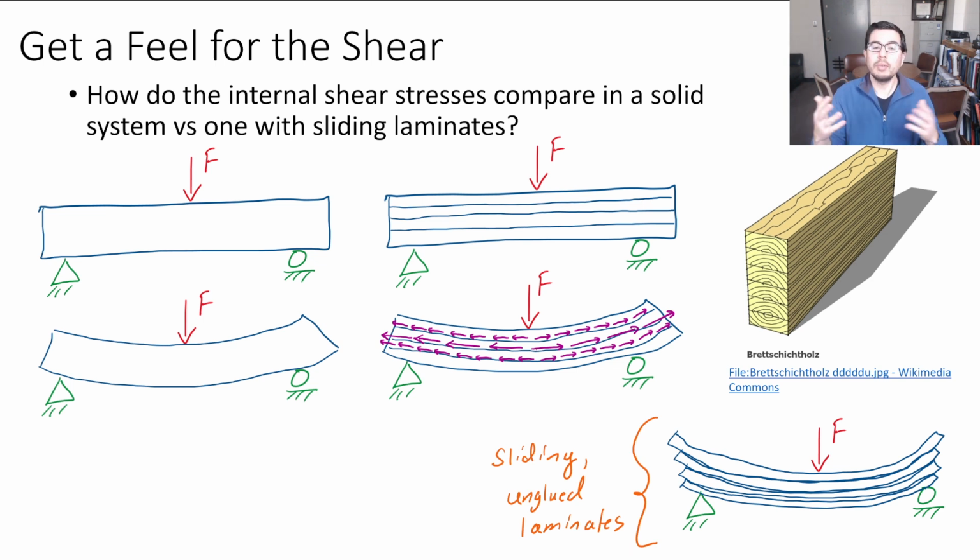I guess not everything in this course is about springs, but there can be spring designs, like leaf springs or different designs, where you might actually want a little bit of sliding between the laminates, and you could control the spring constant, essentially the force versus deflection. But we haven't gotten to deflection of beams yet.